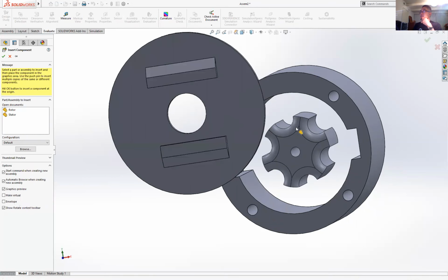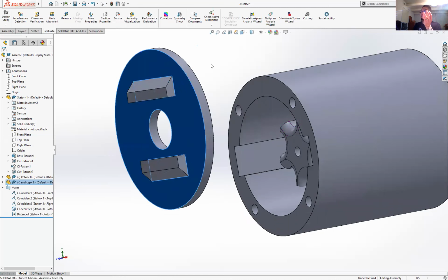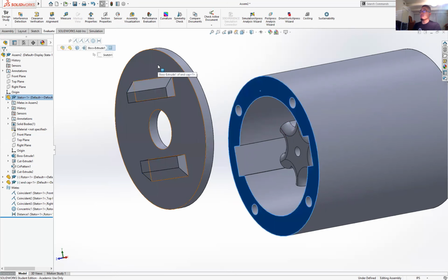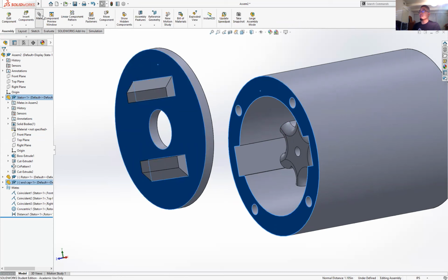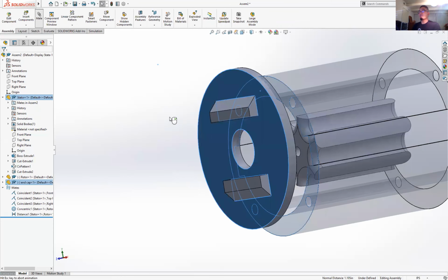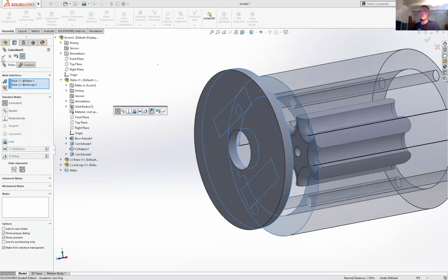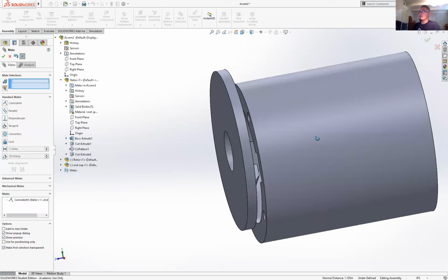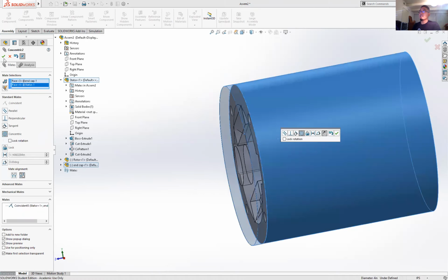So the end cap's there. And so notice it's just kind of floating around. Now let's mate this surface here with this surface. So I control select both. I go to my assembly tab, hit mate. Okay, and we'll go, oh, that's not right. It's not supposed to be mated like this. It's supposed to be the other way around. No problem. You can go over here and you see the mate alignment. You just reverse it. Bang. So hit check. Again, I want to get the things coincident here and here. Good. And I hit check.